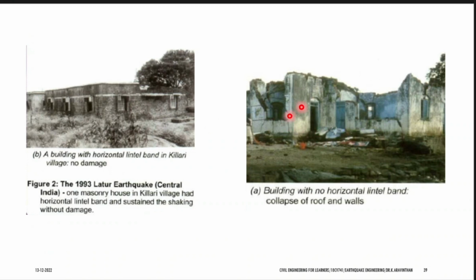Can you observe this failure? Wherever you have openings, at those parts you have the brick. See, this is a window, and above the window you have the brickwork, and at the sides you have the brickwork. Can you see all the failure which occurred will be at the openings? Here you can see an opening and a crack above the opening.